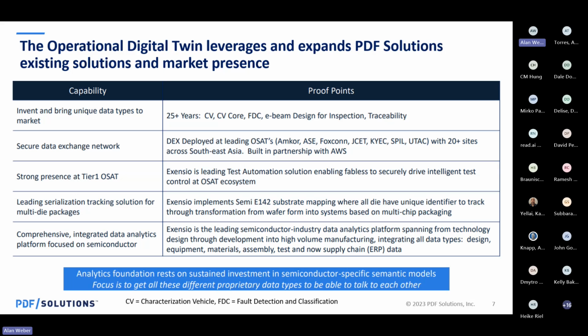And so rather than trying to deduce that from whatever device structures the customer was putting on there, PDF designed special characterization vehicles that combined with special measurement metrology and analysis software that did a good job of doing yield prediction independent of the sort of actual device structure. And so that was one of the core innovations of the company, and that has built from there.